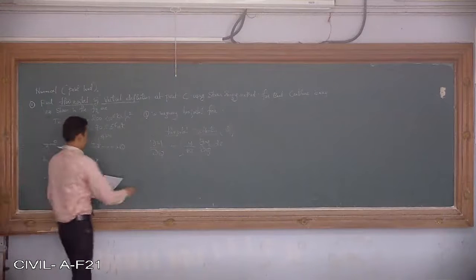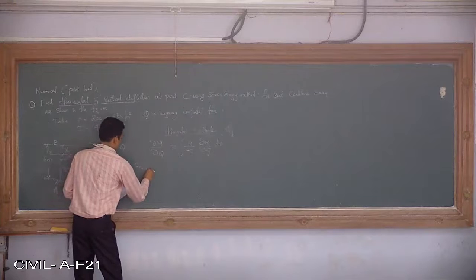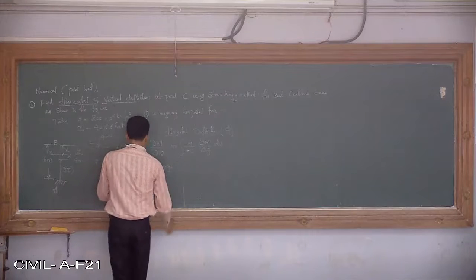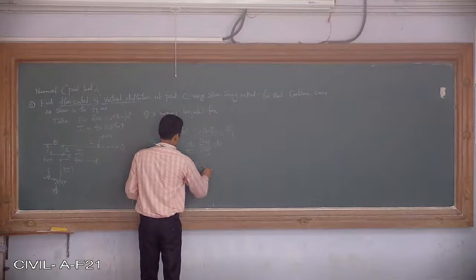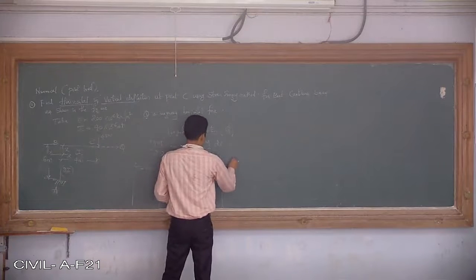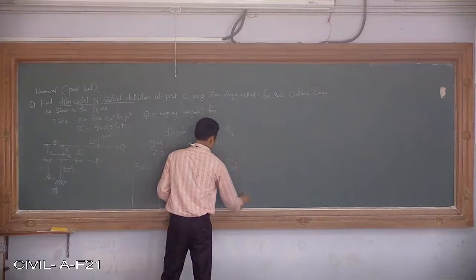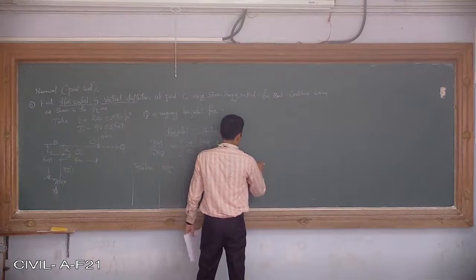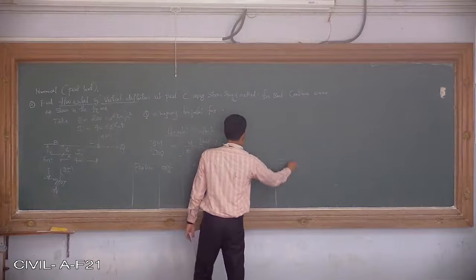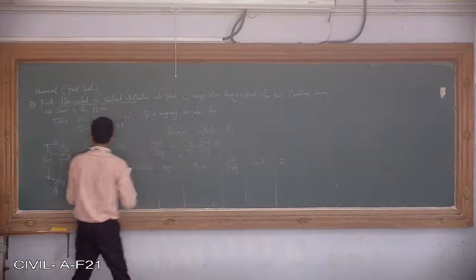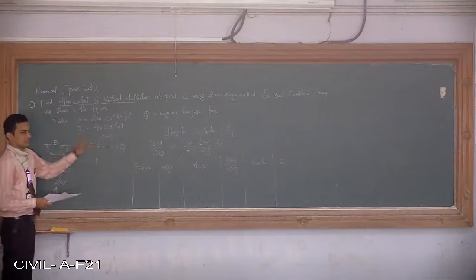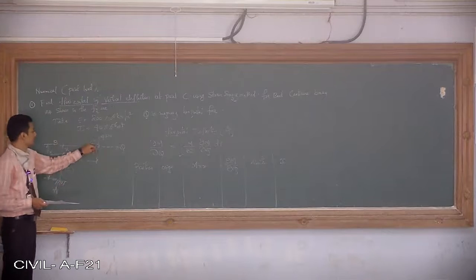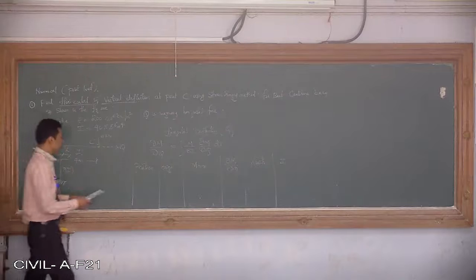Okay. So directly we'll have a table. We have the portion, origin, moment about xx, and dou M by dou Q, the derivative with respect to Q. Next we have limits, and next the moment of inertia I. The portion will be CB, because the terms have changed. I have not taken it as ABC, I have taken it as AB reversed. So first is beam section CB.